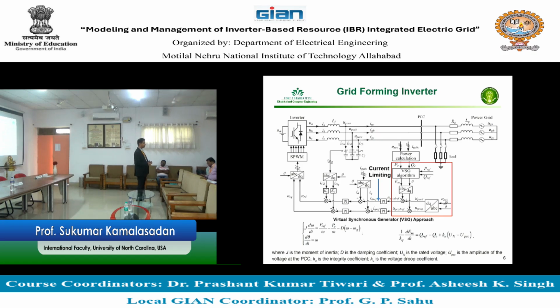So can you write the equations for the entire synchronous generator? Yeah, you can. What equations do you write? Well, you look at a synchronous generator model. The primary fundamental equation for a synchronous generator can be represented as two first order derivatives, or one second order derivative model. Have you heard of the second order derivative model of a synchronous generator? Fundamental? No? This is undergrad. If you say no, that means you are going backwards. If you are working on a research problem, the two equations that are very fundamental for a generator are known as the swing equation. Have you heard of the swing equation?